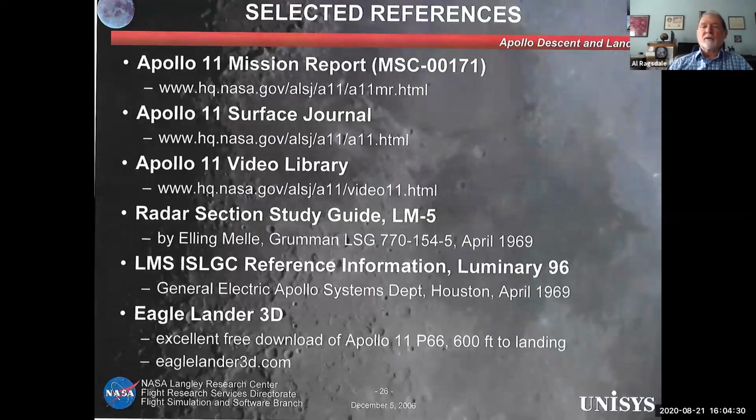And then Apollo 12 almost backed into a crater. He thought he'd landed about 100 feet past the edge of a crater, and they found a bug in the cross pointer that for the last 30 seconds or so, he thought he was coming straight down, and he was actually backing up at 2 feet per second. If he backed up another 10 seconds, he would have hit the wall of a crater, and who knows, it might have tipped over. So we had to add a mod to simulate not landing on a flat surface.